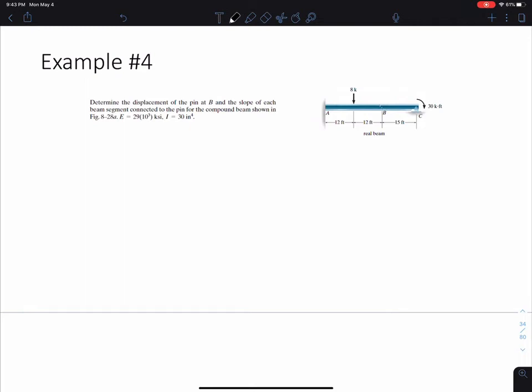Draw the moment diagram and then make the moment diagram your load. But you can imagine what happens when you have a super complicated moment diagram. It starts looking crazy on your beam and you can't even analyze it because it's not from those basic static concepts that we know. So you always want to make sure that you're not doing anything more than a triangular distributed load, a constant distributed load, point loads, and things like that on your beam. Because then it's just not realistic, and the conjugate beam method wouldn't necessarily be the best method to use. So I'm going to show you now what we can do to make sure that our loading is still simple enough to solve and put together.